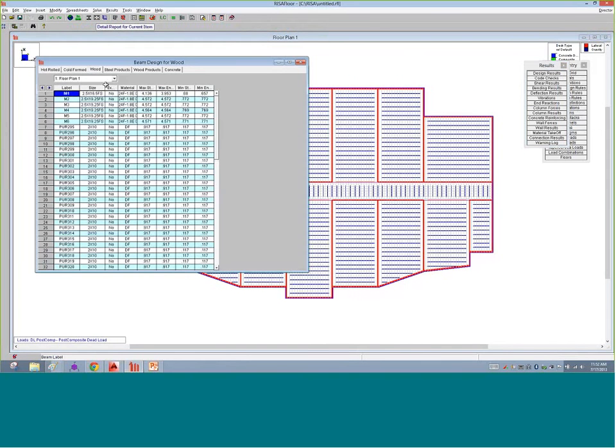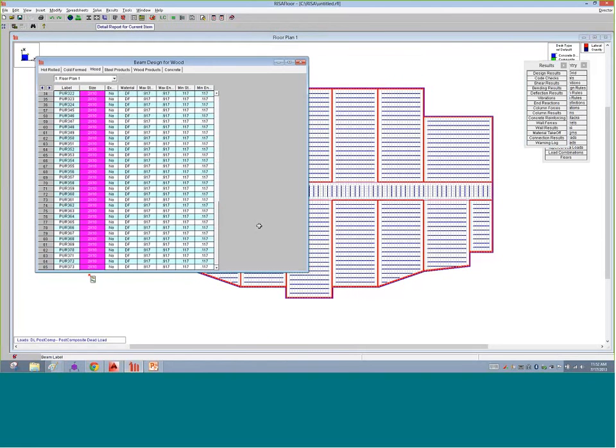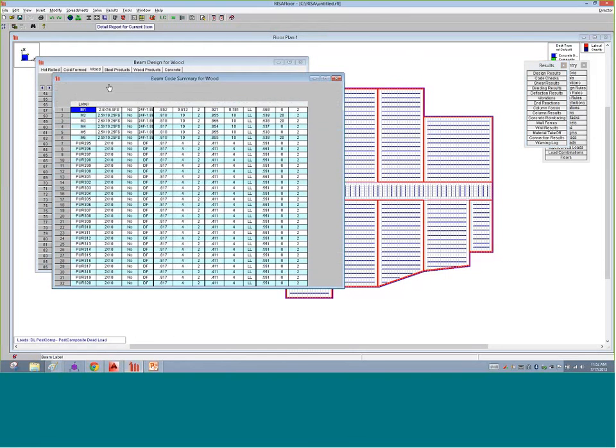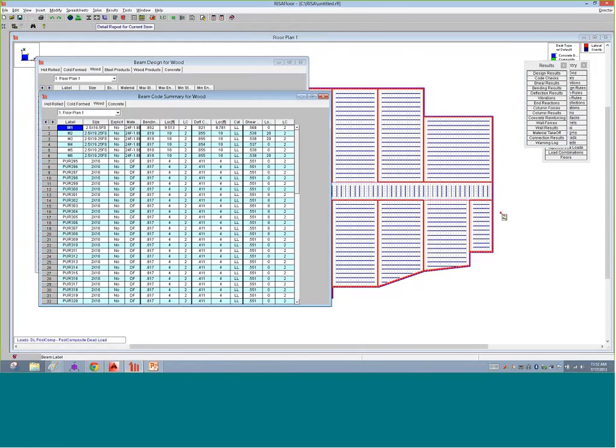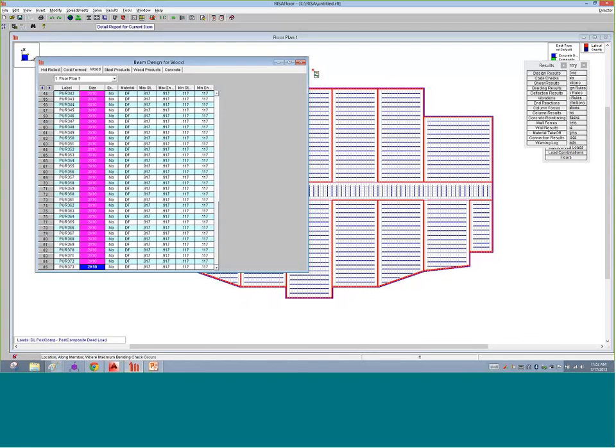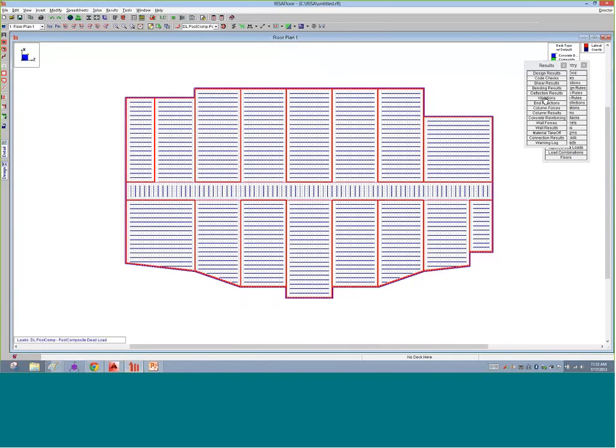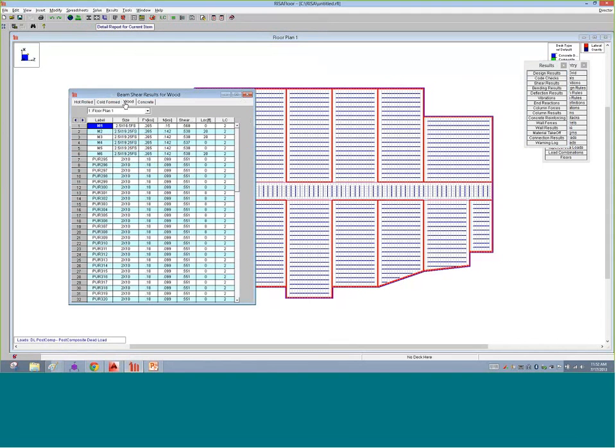We can see here specifically what was happening with your design results. It tells us the size of the members that were designed. We get to see the code check. We have a spreadsheet listing the code check. I love the detail report because it gives me the pictures and the graphics, but when you're looking at a whole structure, it is helpful to see, as a one-off, what's going on quickly in the structure. It tells us what the code checks were, the governing load combination, the locations, things like that. So it's nice to see that for a full building. You can have all of those spreadsheets give you a nice breakdown per different types of things.